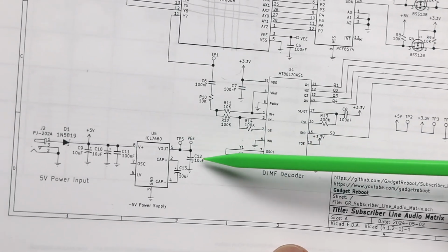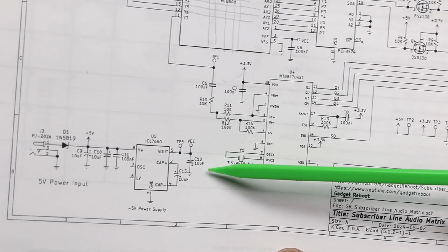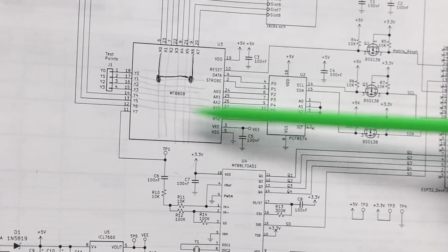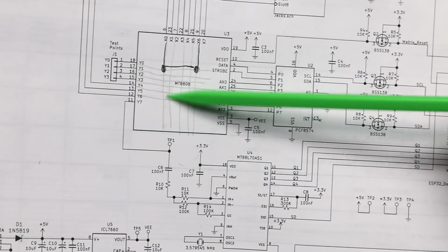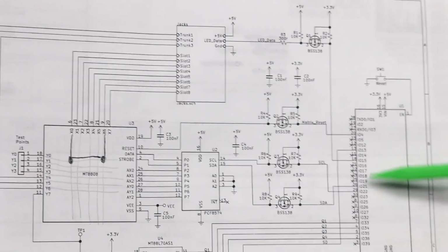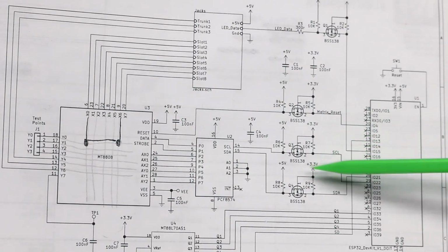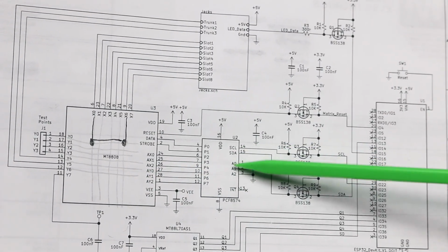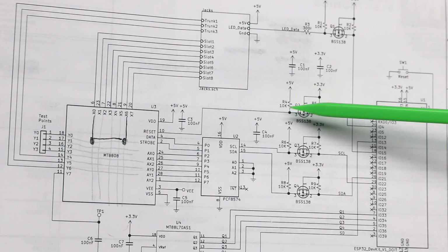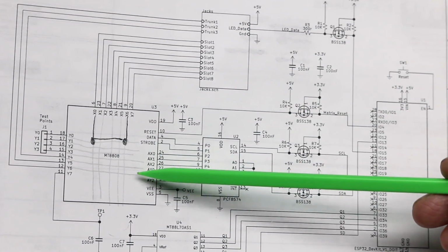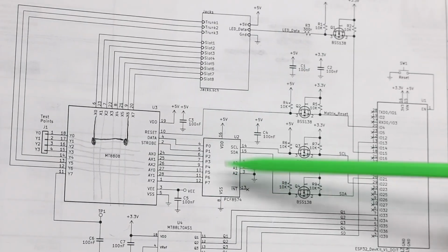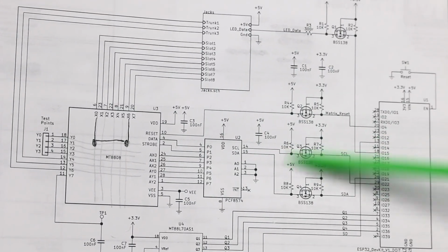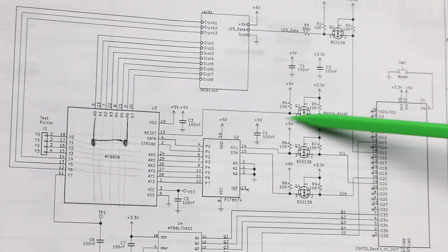Then I have a negative voltage rail generator. I'm powering the board at +5, so this generates -5. Then on the analog matrix, I have +5 and -5, so I can have audio signals passing through. Since the ESP is running at 3.3 volt GPIO, I need to talk to the analog matrix at 5 volts, so I'm using FET level shifters to go from 3.3 to 5, and I'm controlling the 8808 matrix with a PCF8574 GPIO expander. So that's I2C with the level shifter and another dedicated control line with a level shifter.